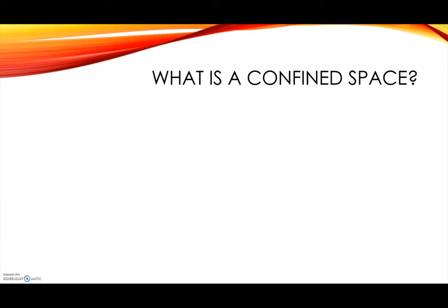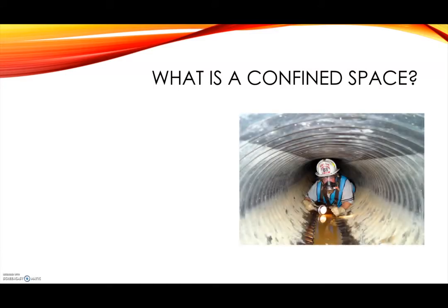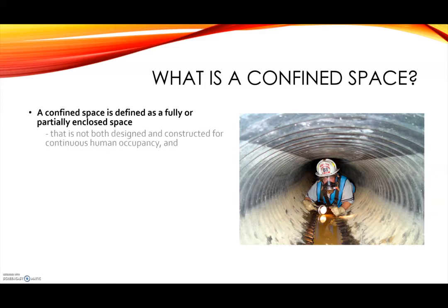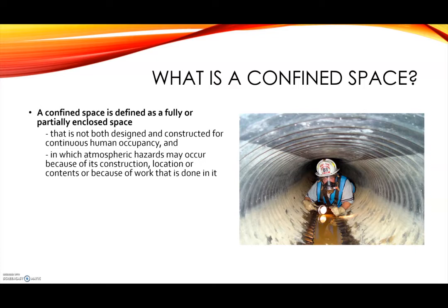What is a confined space? A confined space is defined as a fully or partially enclosed space that is not both designed and constructed for continuous human occupancy and in which atmospheric hazards may occur because of its construction, location, or contents, or because of the work that is done in it.